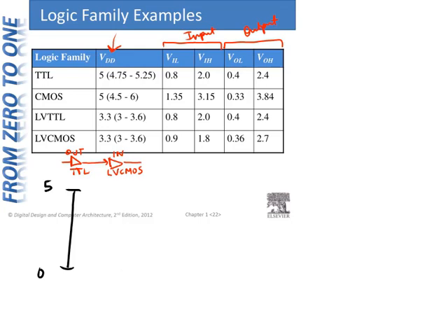It doesn't have to be completely accurate, but at 3.3 for the high value and 0 for the low value. So we're interested in the TTL output characteristics and the low voltage CMOS input characteristics, because the low voltage CMOS is the receiver. Just by the way, I've defined the problem.